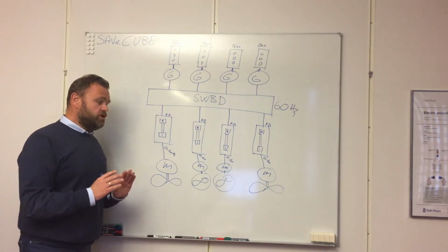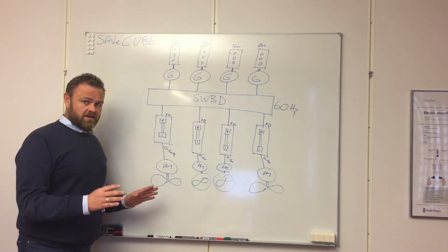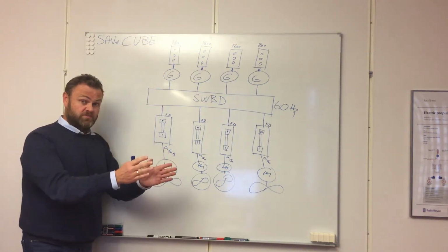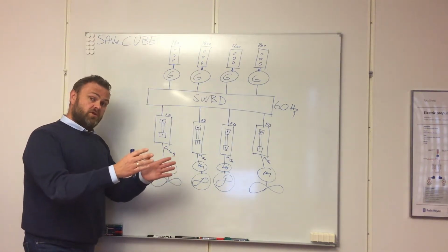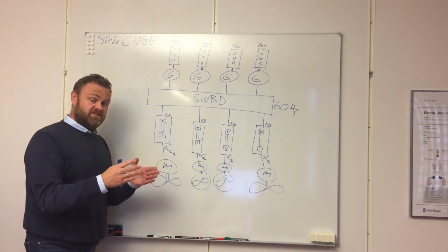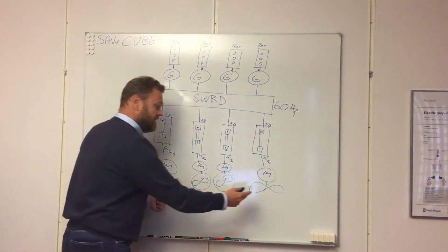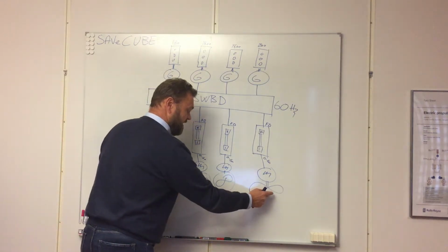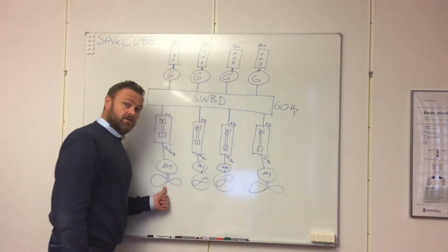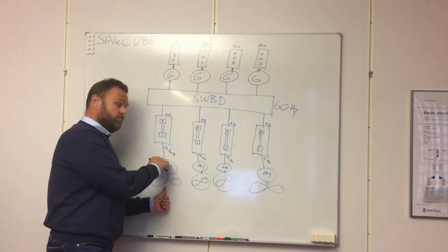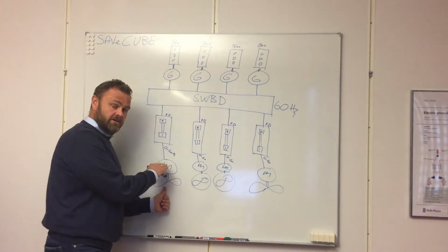So if you are not sailing your vessel at full speed ahead, but you are adjusting the speed of the vessel down, then immediately you can save fuel from regulating the RPM on the propeller down.